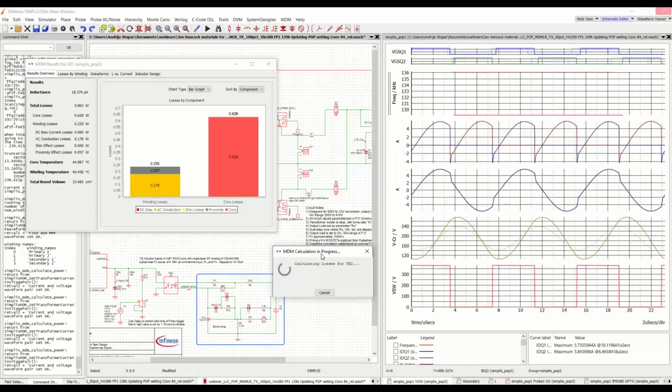No. In any case, we can say that the core loss is calculated in a post-processing step. So what we have in the circuit schematic is just the DCR of the windings, just the winding DC resistance. And that is what is affecting your circuit waveforms. There isn't a resistor put in there, for example, to model the core loss. That's highly nonlinear.